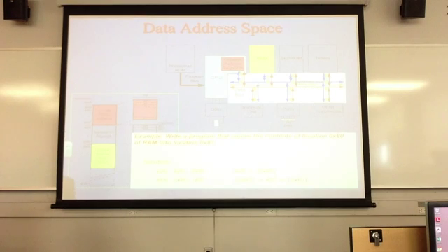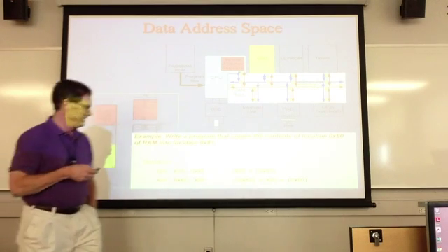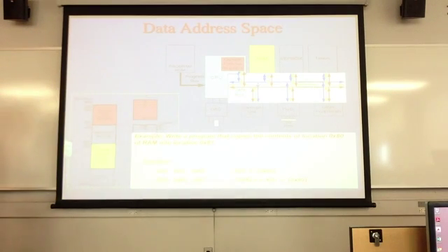All right, write a program that copies. All you're doing is just loading a hex value into R20 and then writing it there. Here what we're going to do is add the contents of location 90 and 95 and store the result in 313. So you just load 90 into one register, 95 into another, and then you simply do an add, and then we do a simple write. Now again, this is processor specific, so you have to know what processor you're using and where you're writing to.